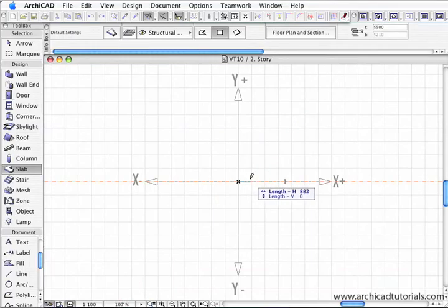So once again, if I start moving in this direction and I type 5000, and if I hit enter, it disappears, because what's actually happened is I'm on the polygon construction method. I've just created a slab that's 5 meters long and 0 high, so it's going to disappear.